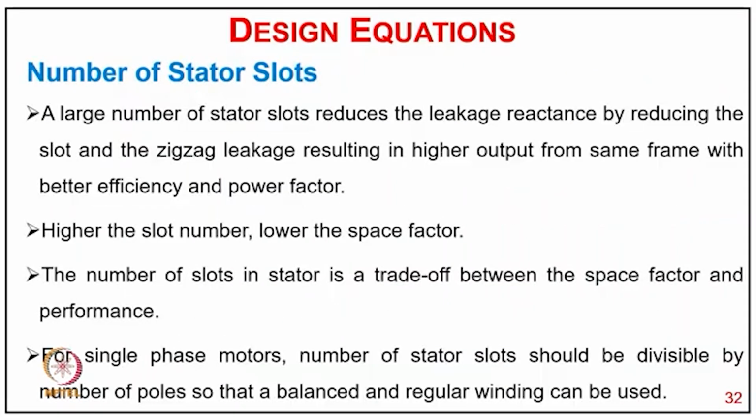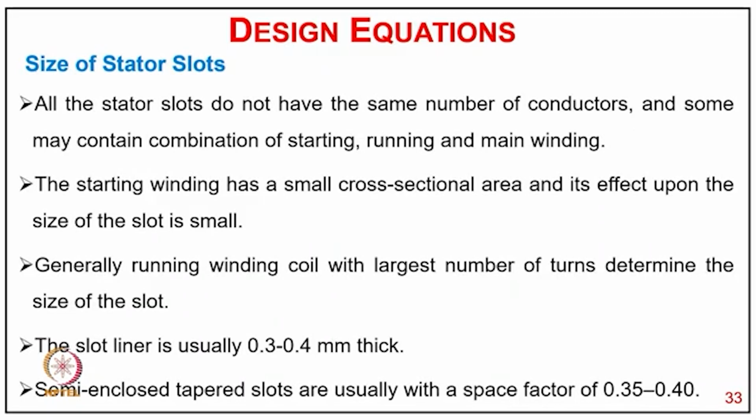Similarly, now we can come to the number of stator slots. A large number of stator slots reduces the leakage reactance by reducing the slot leakage reactance, resulting in higher output from the same frame size at better efficiency and power factor. So the higher the slot number, the lower the space factor. The number of slots in stator is a trade-off between the space factor and performance. For single phase motors, the number of stator slots should be divisible by the number of poles so that a balanced and regular winding can be used.